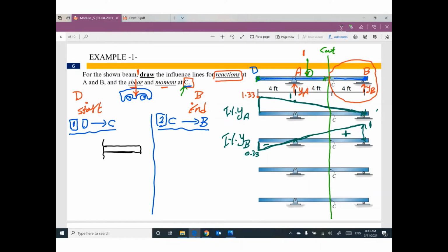I did cut here. We have vertical reaction here, YB. At your cut, we have shear. Would like to rotate this part of the beam clockwise. And we have moment, would like to make this part of the beam to smile. So we have MC, we have shear at C. Go ahead and apply summation F of Y equals 0. We have positive V at C. We have positive YB equals 0. So V at C equal negative YB.